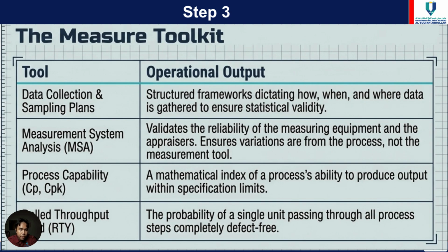MSA validates the reliability of the measuring equipment and the appraiser, ensuring variation comes from the process, not the measurement tool. For process capability, we calculate using a given formula to produce output within specification limits. And then RTY is the probability of a single unit passing through all process steps completely defect free.